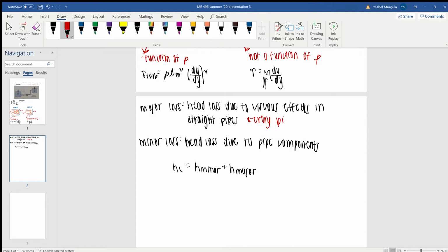because in every pipe there is going to be interaction between the fluid and the pipe causing some viscous effects. This is all due to the no-slip boundary condition, which we learned previously in the course. The no-slip boundary condition says that fluids will interact with the surfaces that they touch, so they can't just go through a pipe and not react with the wall. There's going to be some friction or some force due to the viscosity of the liquid and some shearing stress